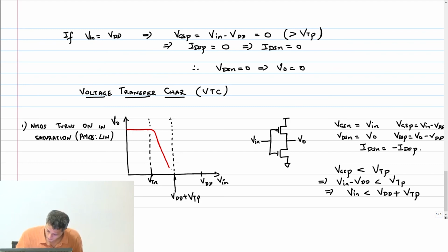Okay, and this will come all the way down here, and then of course the output will be absolutely 0 after that. Why? Because now it's an ideal transistor. PMOS transistor cannot tolerate any more current. Therefore, what should happen to the VDS of the NMOS transistor? 0. Okay.